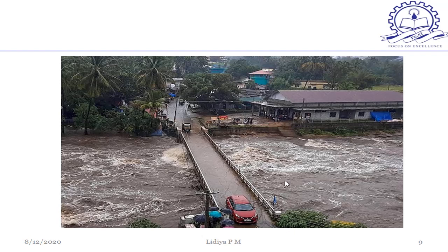I can give you a very good example of the best flood management system in India that was designed by Sir M. Visvesvaraya. Hyderabad faced a devastating flood on 28 September 1908. The river Musi flooded the streets of the city after a torrential rainfall due to a cloudburst. In order to control the flood, Visvesvaraya suggested the construction of two storage reservoirs, Osman Sagar and Himayat Sagar, above the city of Hyderabad, across the river Musi and its tributary river Esi.